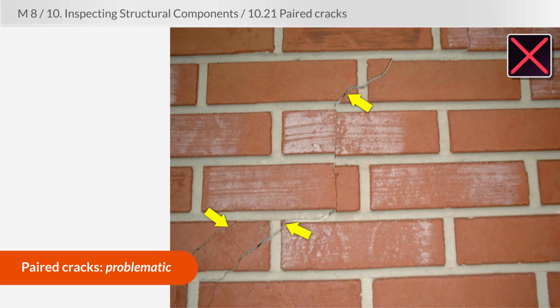These are problematic cracks. And you would definitely recommend further evaluation either by a foundation contractor or a licensed structural engineer, really depending on what you see at the foundation level.